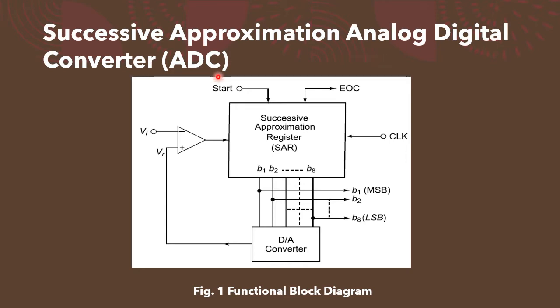In this type of ADC, it consists of one successive approximation register, SAR, and this register SAR creates its own bits. When a clock pulse is given, an approximation of bits is generated. It will occur when the start bit is 1. If the process ends, that means this EOC, end of conversion, will be 1, then automatically the process is over. That is the meaning. And here the generated bits are given to the DAC, digital to analog converter.